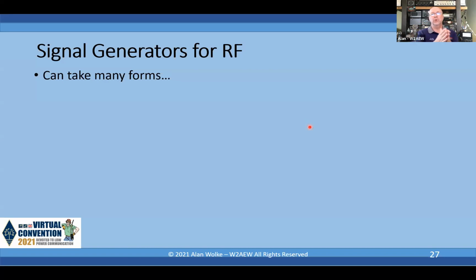So if you have a higher frequency signal, the same amount of time will be a larger phase. The group delay measurement takes the frequency portion and convolves that out, so you just get the raw delay number in time, okay?